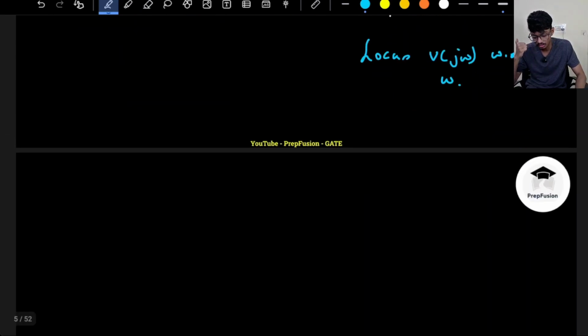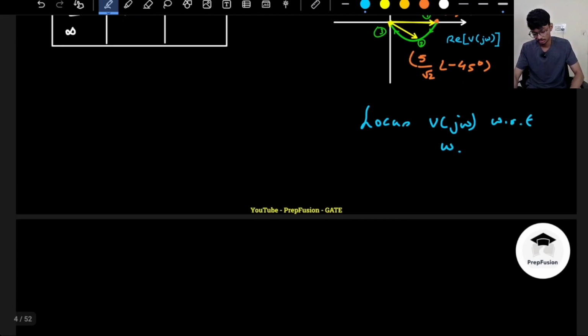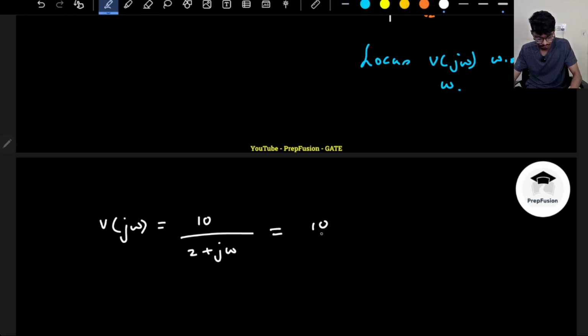Now let us come to the proof of why the shape is a semicircle. For that we have to use a bit of mathematics. So what is my V of j omega? V of j omega is 10 upon 2 plus j omega, right? Now let us rationalize this thing.